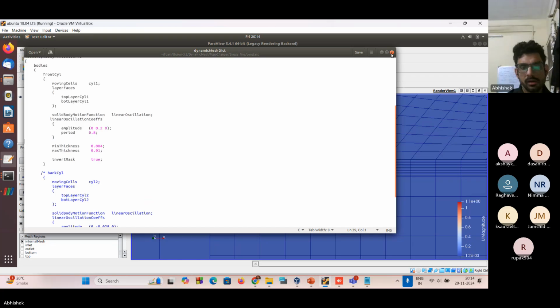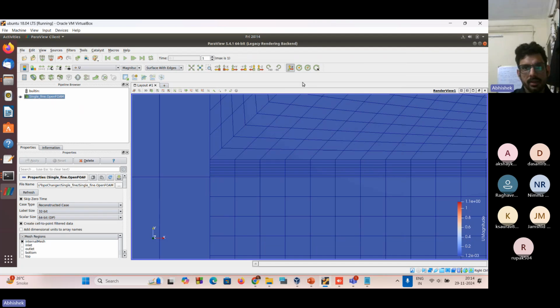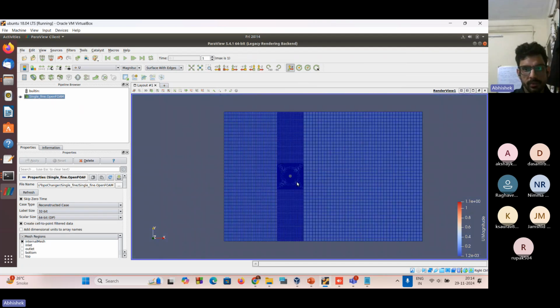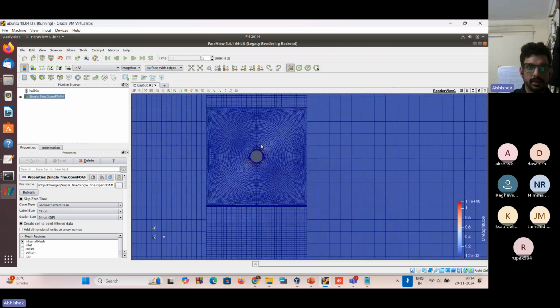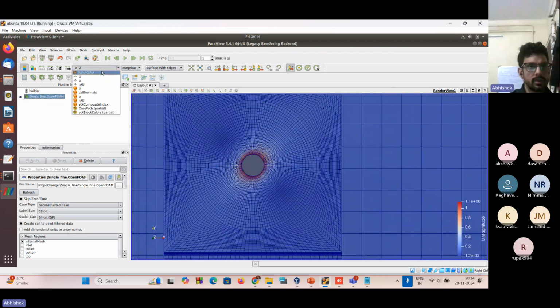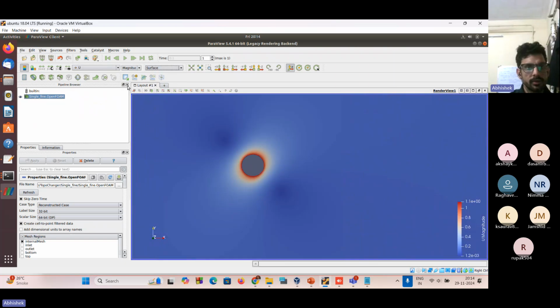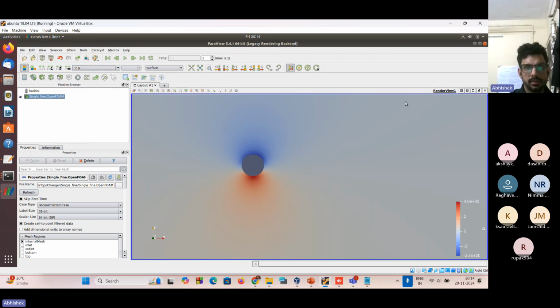All right. So if you are able to get good optimum mesh sizes for each block here, you will be able to get your simulation running. And this is very good for multiple cylinders intending. In the initial time steps, it is running good, but as the simulation is progressing, it is giving us some problem. Initially, it is running good.